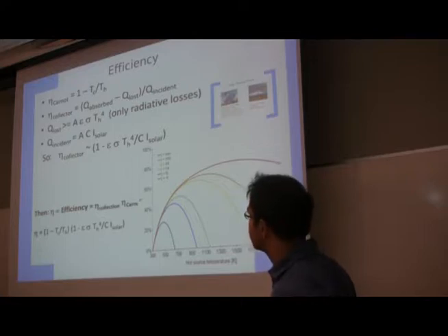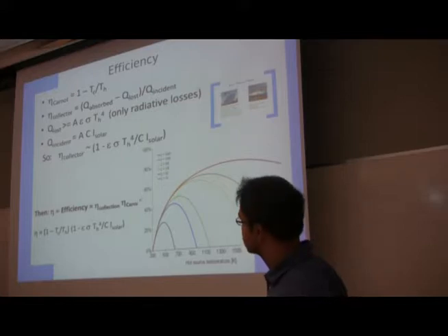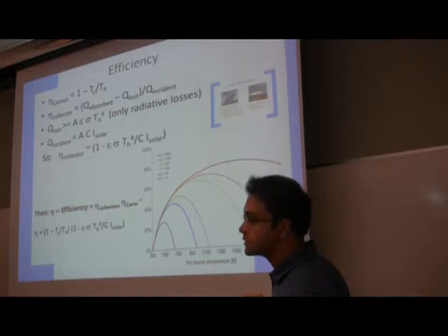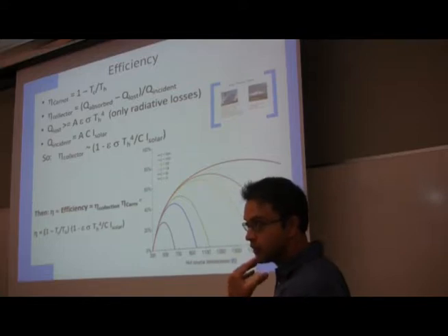Obvious, right? Now, the heat loss, if you only include radiative losses, remember we have convection and conduction, but I'm ignoring them for the sake of simplicity. If you only include radiative losses, then you can use the Stefan-Boltzmann law, which we saw last time, right? Remember, what does the Stefan-Boltzmann law say? It says the flux, the power density, integrated over the entire spectrum of interest, of a radiating black body is given by sigma T raised to the 4th.